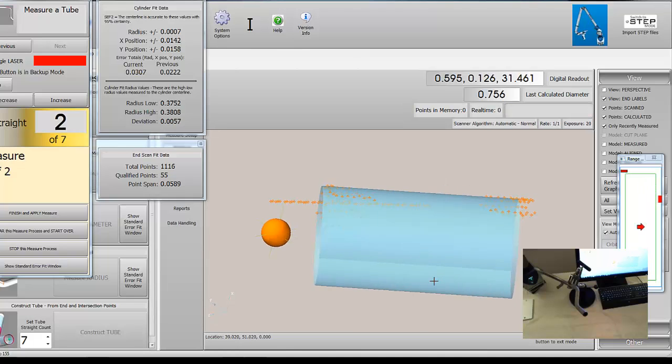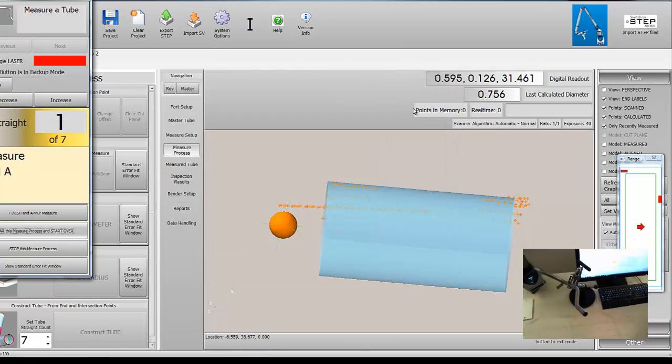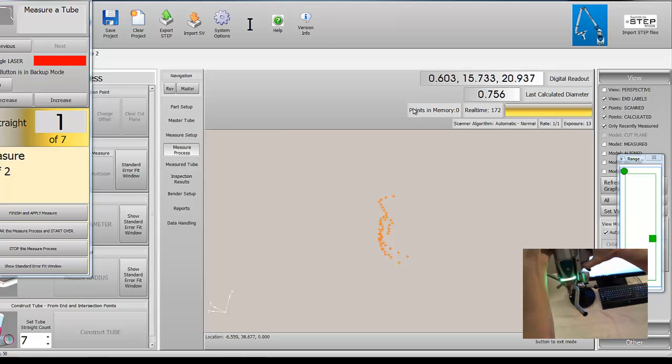This is also the least accurate orientation because the points in the stripe are spread out more relative to the end. Now let's compare this technique to scanning the actual end wall. Scanning the end wall concentrates the points at the true end of the tube.